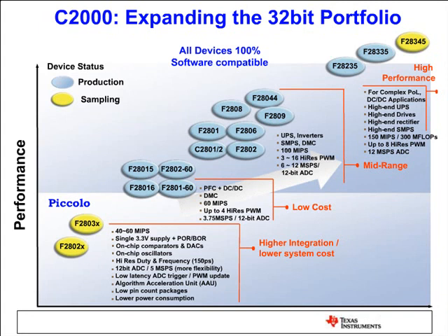But on the other hand, for motor control applications, high resolution duty cycle and high resolution frequency is not very effective, because for motor control we are working with large amounts of currents, and the frequency is quite low, like 10K switching frequency or 20K switching frequency. On the other hand, when we are talking about digital power supplies, it's more than 100K frequency mostly. So that's why the high resolution feature becomes very important for DPS, digital power supply applications.